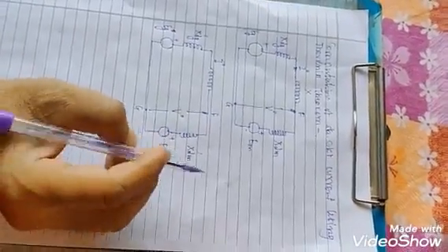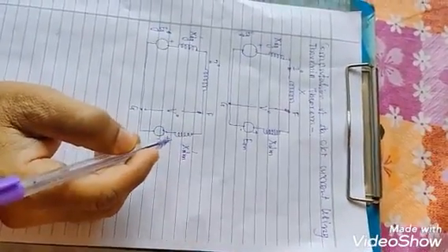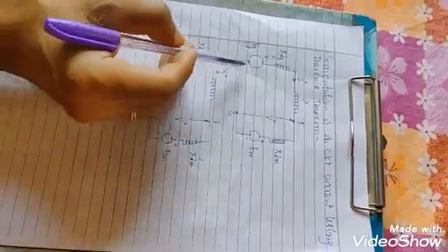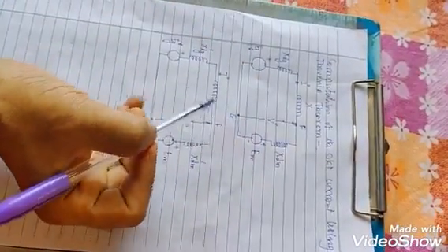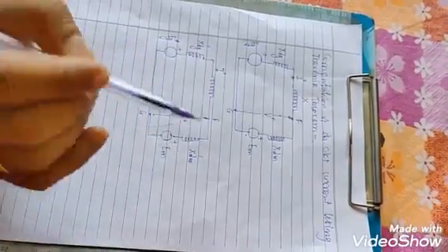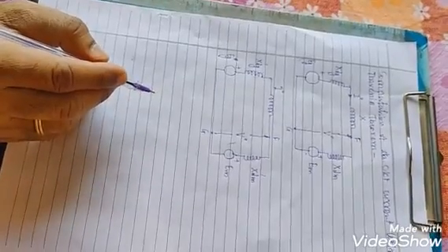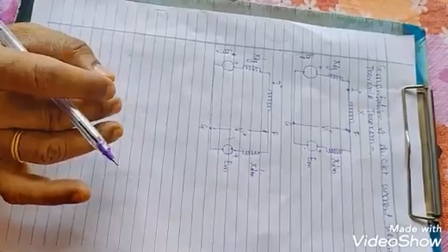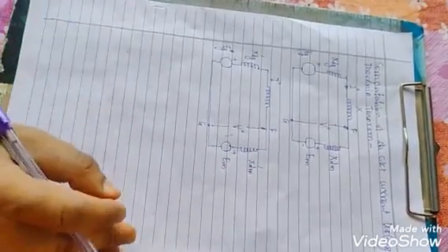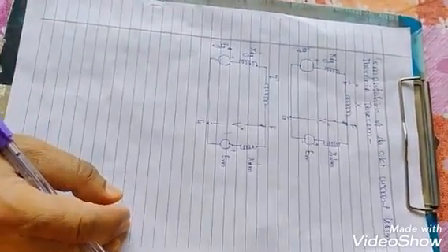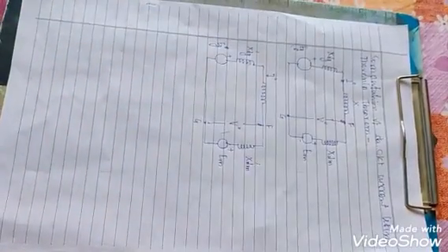Here we are interested to determine the transient current delivered. Now if we are interested to determine the subtransient current delivered by the generator, then we have to replace the steady state model by subtransient reactances. This change does not disturb the pre-fault voltage V0 and the current I0. Now applying Thevenin's theorem to this model.